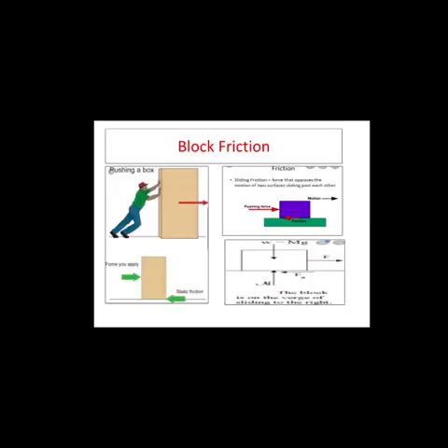With an increase in the unbalanced force or the shear force across the section, the shear stresses also increase, and at a certain load, the stresses may reach their maximum value that the cross section of the material can offer. Any increase beyond this point would lead to failure in shear. The maximum shear stress that any cross section of a given material can offer just before failure is called its strength in shear, or shear strength.